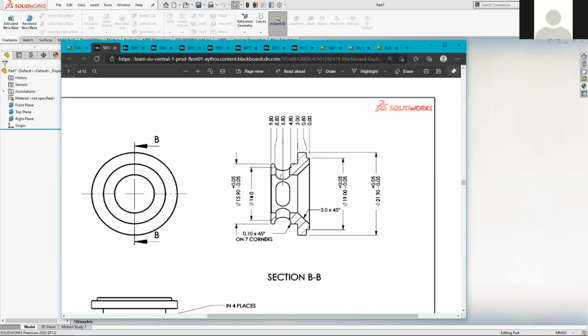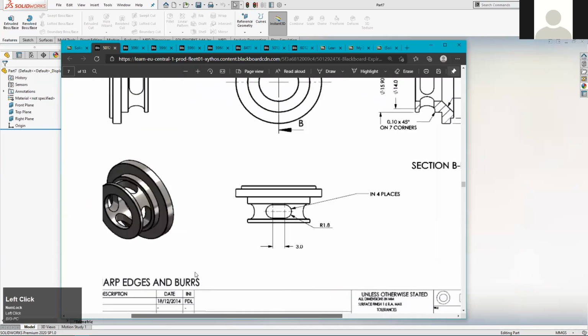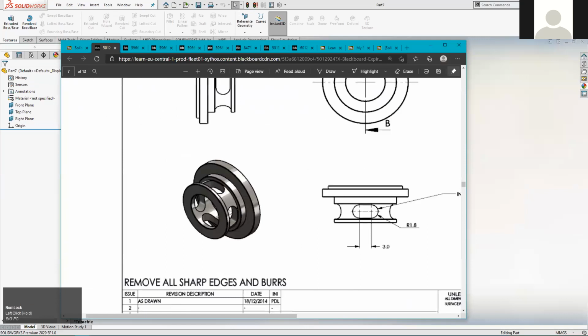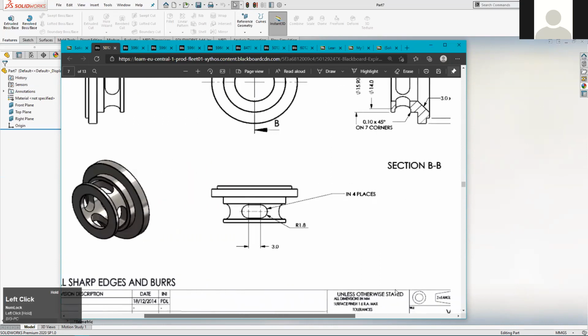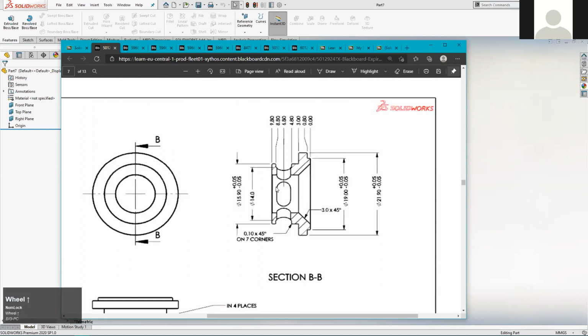Now we're going to disregard these slot shapes that have been cut into the part. You can see in the 3D view of it here, it has these slot shape sketch extrudes cut through it. But certainly for our first feature, we're going to disregard those. We're going to intend to put them in subsequently using a cut extrude and then using a pattern as well. So we're going to imagine that this shape continues all the way along there. That's a continuous horizontal edge.